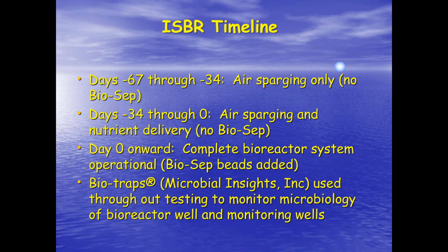Now, we're going to be adding air, and we're going to be adding nutrients. So a perfectly relevant question is whether or not just adding air, or just adding air and nutrients, to the aquifer will result in stimulation of some of these BTEX hydrocarbons that have been mobilized in the groundwater.